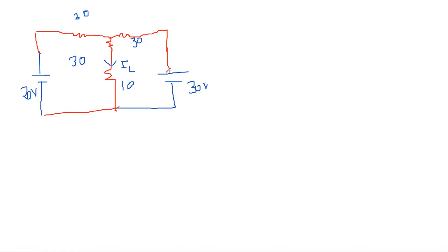So this is your circuit. Now, what are the values of these three resistances? They are not 30 ohms now. If you convert a delta into a corresponding star, then these values will become 10 ohms each, because all the three delta values were 30.